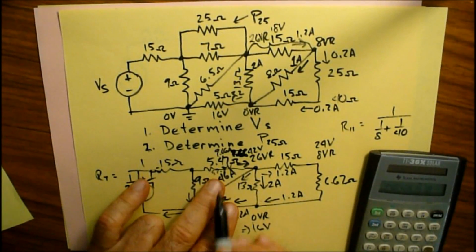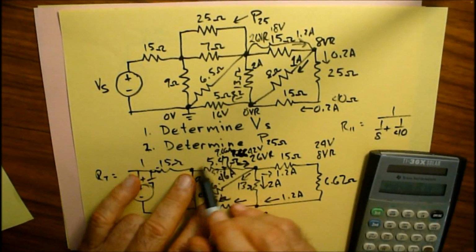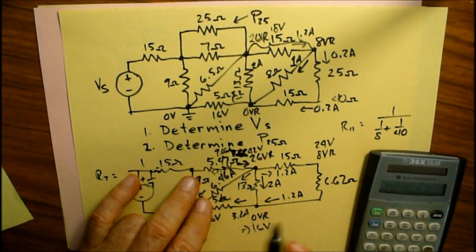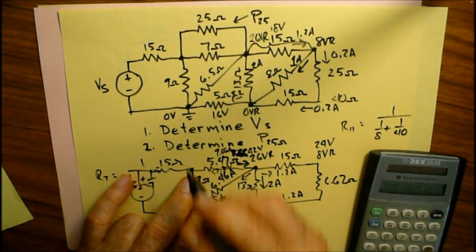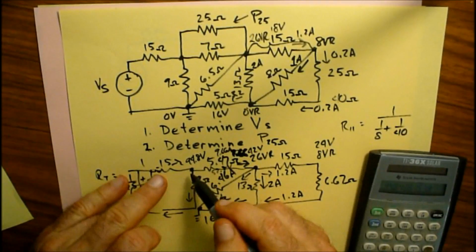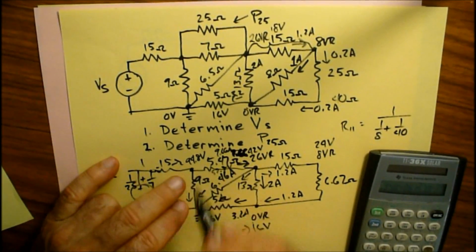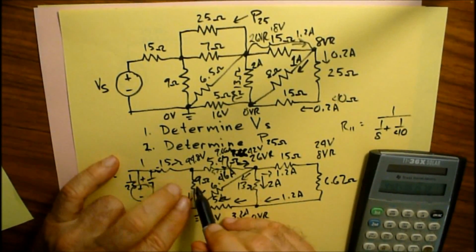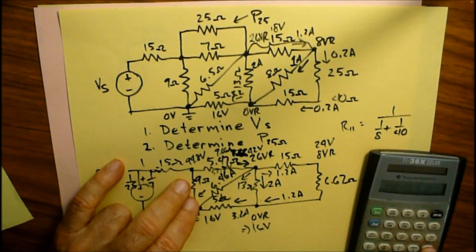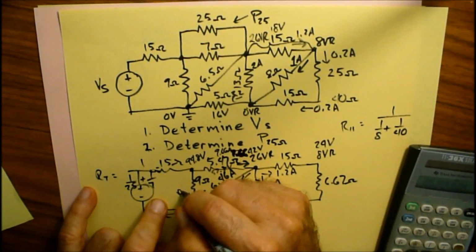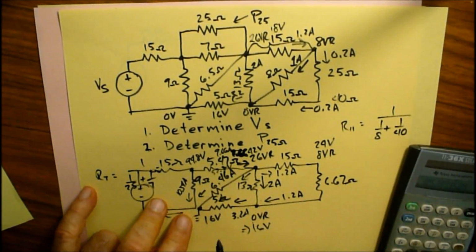And that's a 52.8 volt drop across this resistor, but the current's going from high to low, so we add that to this 42 volts, and that gives us 94.8 volts right here at this point. Okay, so 94.8 volts, and here I have a 9 ohm resistor, so divide by 9, and that gives me 10.54 amperes going this direction.